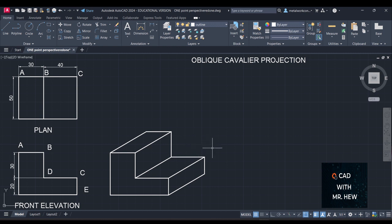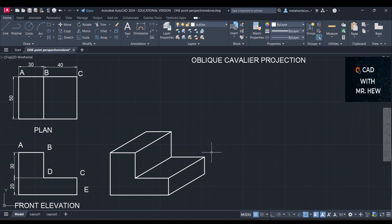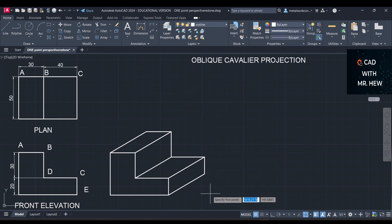Good. All right. The other way that you can draw this drawing is the same drawing, but the angle can be 45. And we normally use 45 when we're drawing cabinet cavalier projection or drawing, if you would prefer to call it drawing. All right. So we're going to do the same thing again. So we go line. We start here. So we're starting here, go line, or here.